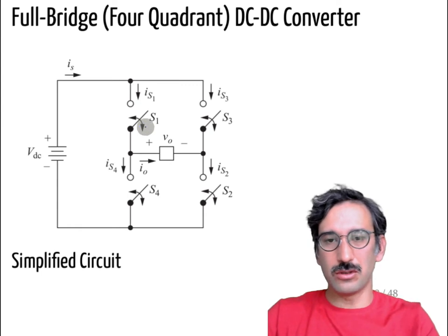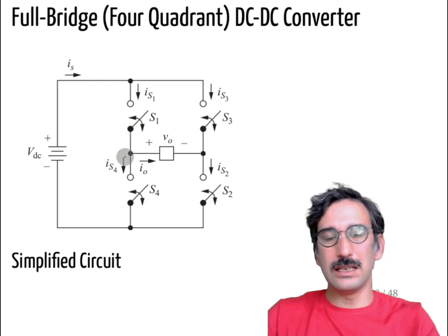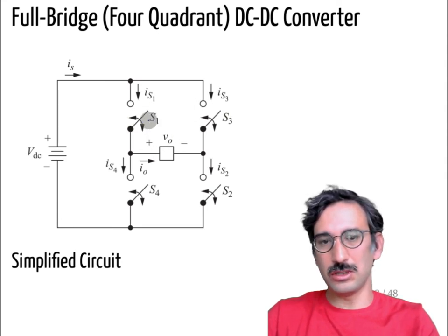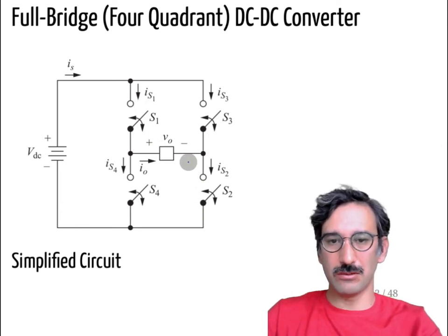Okay, of course, what you don't want to do, this is a voltage source converter, you don't turn on switch 1 and switch 4 at the same time simultaneously, because that will create a short circuit. We don't want that, but you can turn on S1 and S3, so it will be like a 0 voltage here, or S1 and S2, you will have some voltage here, vice versa.